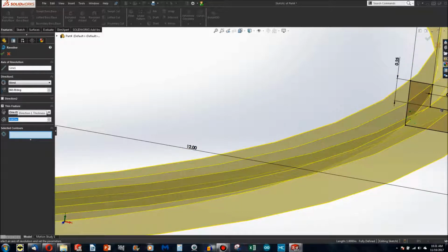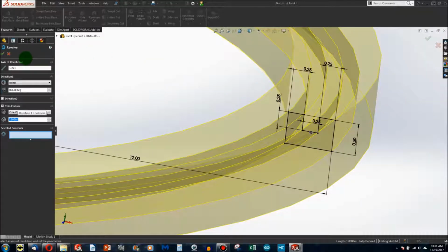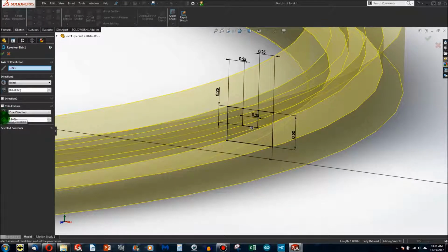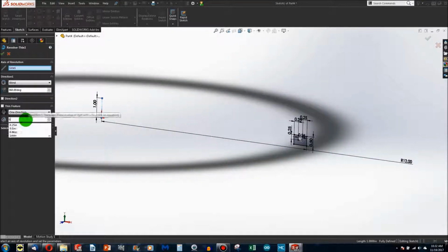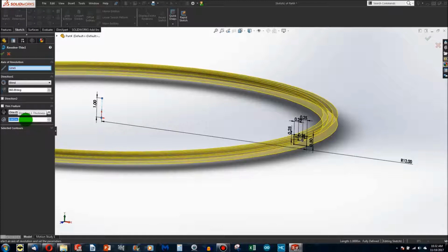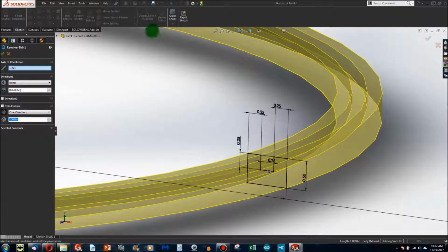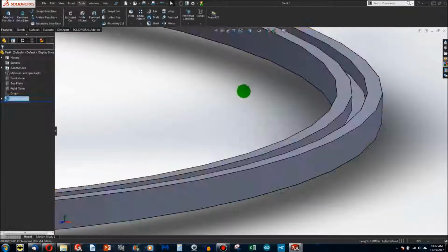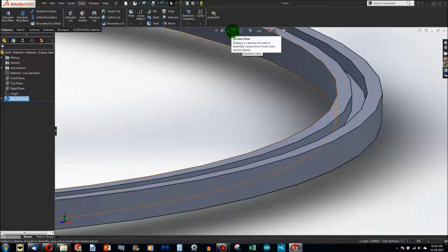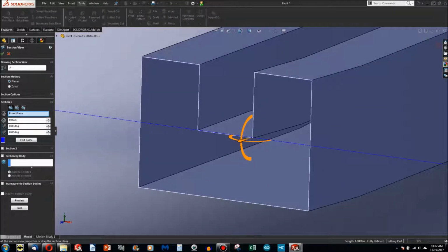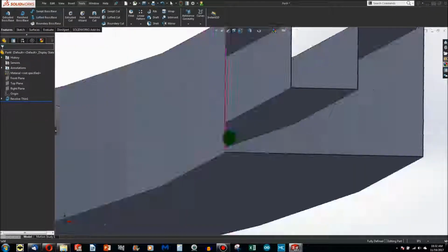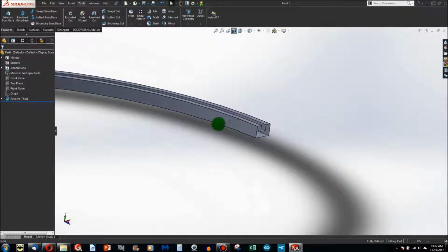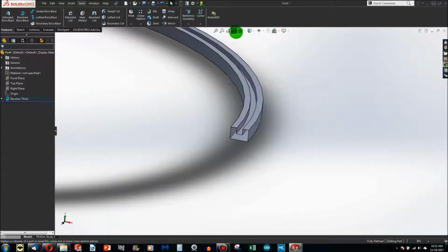So if I go 2/1000ths of an inch thick, you can always specify the other direction. And make it 2/1000ths in the other direction. And when I section it out, you can see that it made it a hollow thin feature 2/1000ths of an inch thick. So you can do the thin feature if you want to make some hollow features.